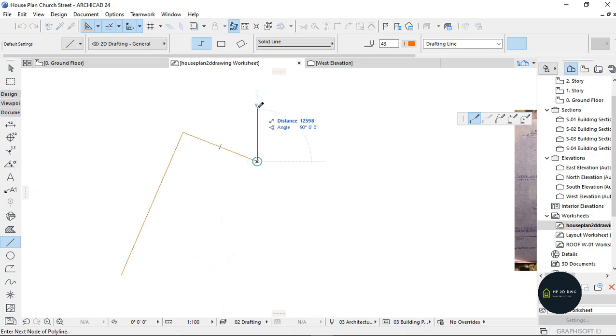So you raise up the line. Make sure it's in 90 degrees, and go 90 degrees. And you do for this other side, which is 202 degrees. Click on tab, 202 degrees, spacebar, 41 minutes, and minus. And you change the distance. The distance is 36600, and click enter twice.